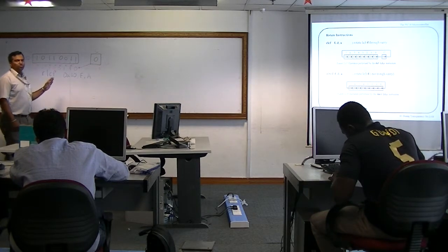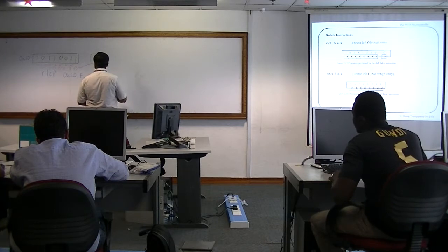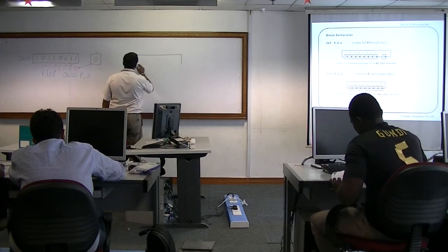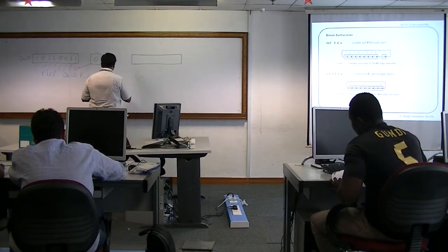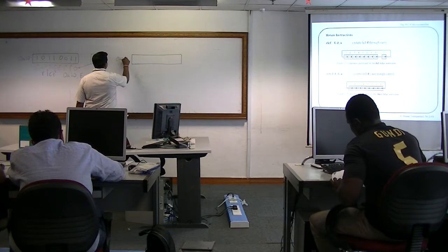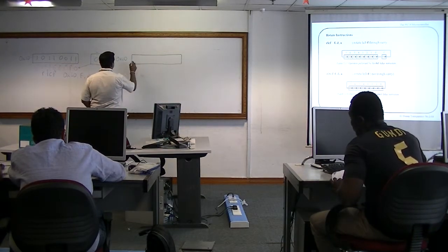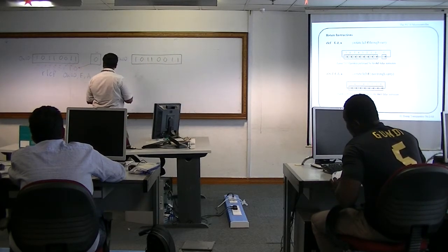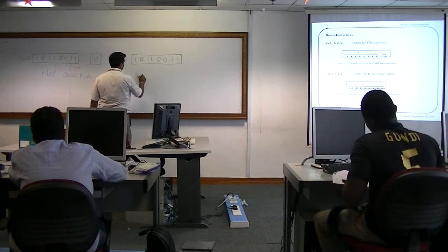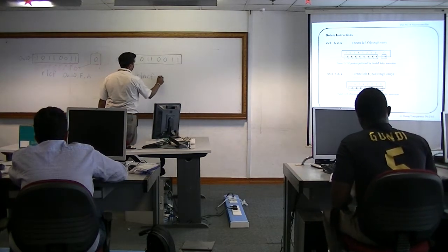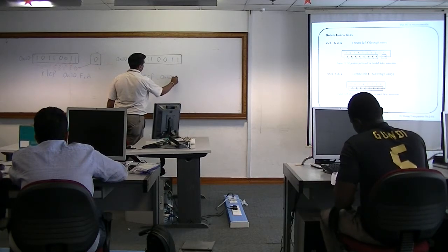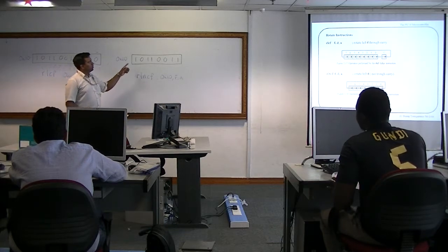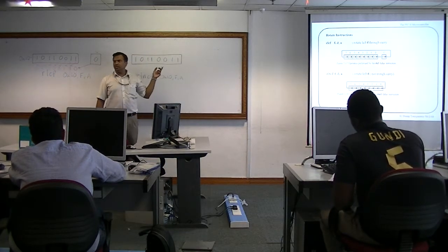This is rotate left through carry. There's another one, rotate left not through carry. Let's take the same 5 register so that you can see the difference between one rotating through carry and one without carry. So the same data: 1, 0, 1, 0, 0, 1, 1. So the instruction is going to be rotate left, not through carry. Like this. So this one only rotates within its file register.